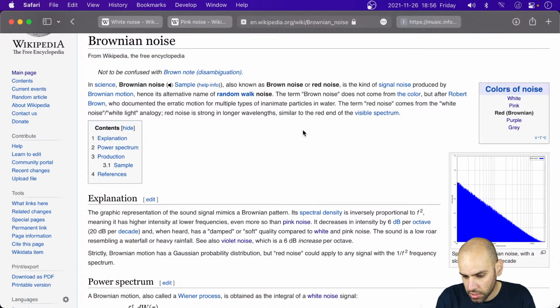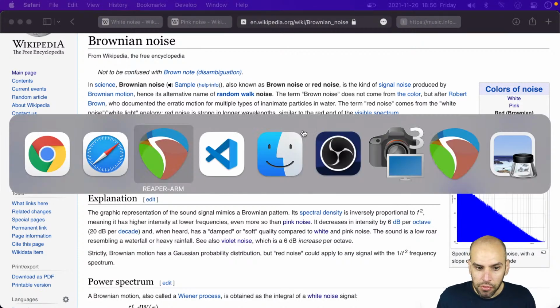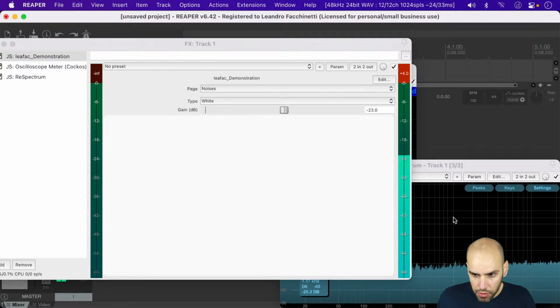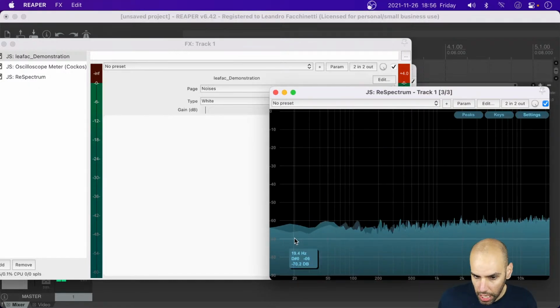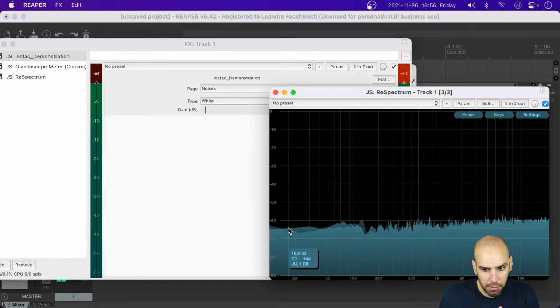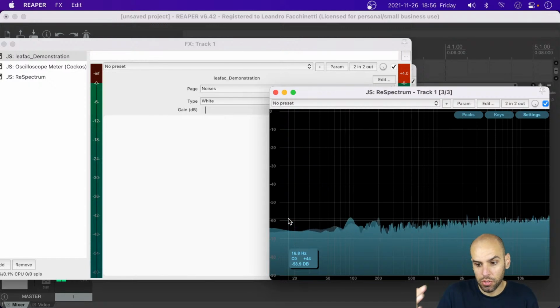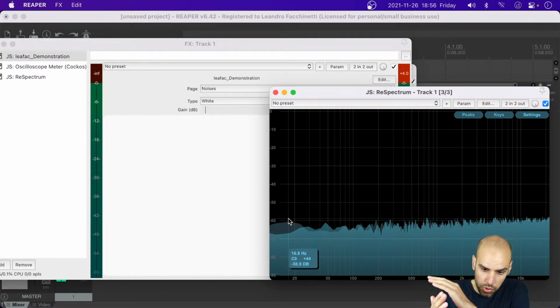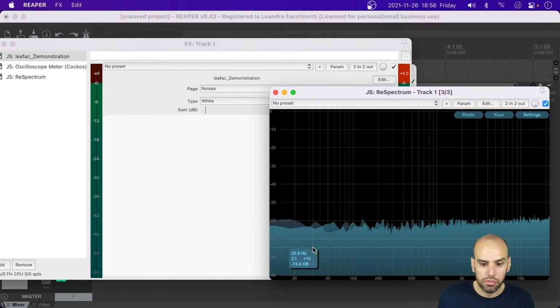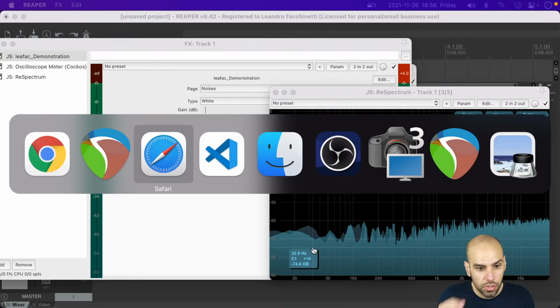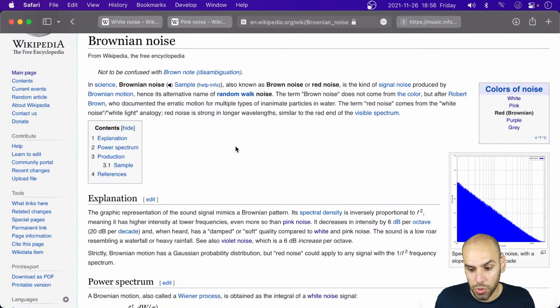Yeah, and Bo says that he uses white noise all the time to test his coding. And yes, white noise is useful because if you are doing something like a filter, then you can just feed the filter some white noise. You know that the white noise is going to be almost like a flat line. So if your filter is doing a low cut, you'll see all these low frequencies going away, for instance. So yeah, it's a very good testing noise to use.